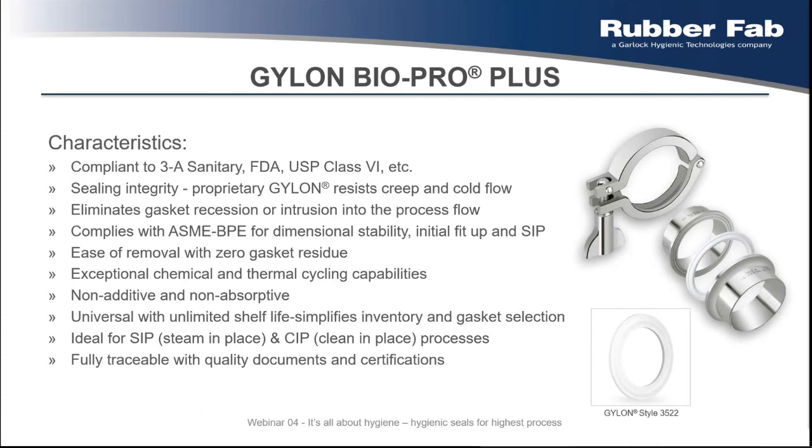Most chemicals we encounter in production processes for the pharmaceutical industry do not pose a threat to PTFE. Of course, there might be exceptions, but the gasket resists chemical and thermal cycling very well. Because of the extremely dense and extremely smooth surface, it is non-absorptive: nothing sticks to the gasket, nothing adheres, and nothing is absorbed by the gasket.